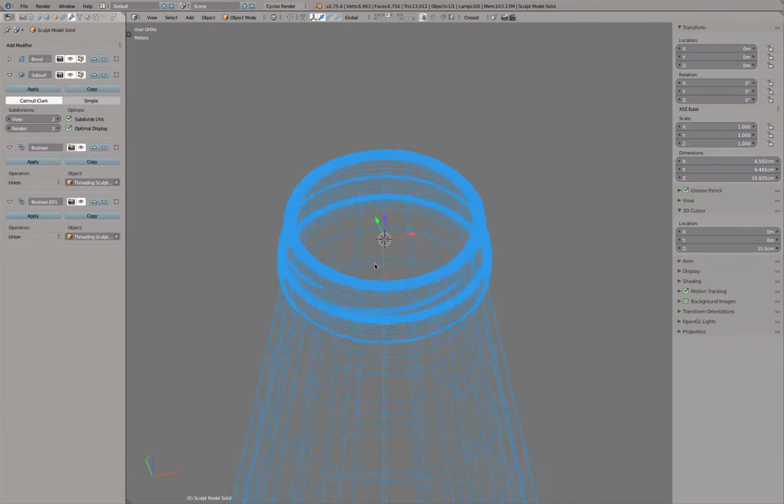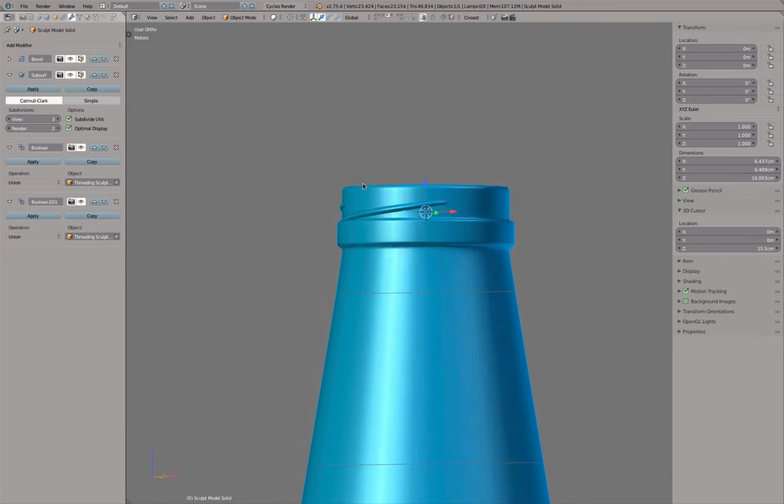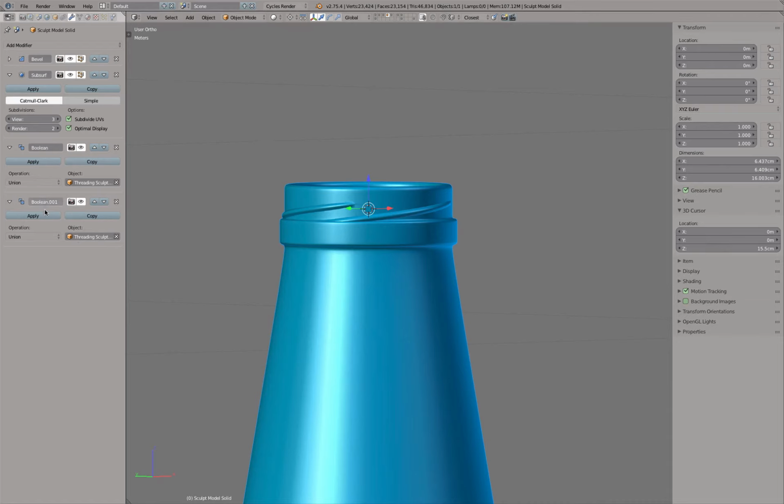If I go into wireframe mode, you will see how this geometry was added to it. And if I switch view here to 2, the results will be a tick better. But the higher the view level, the more polygons there are and the more the software has to calculate, so the longer the delays are. So try to keep this always at a 2 or 3. Never go to 4, 5, or even 6. I could, for example, now simply add the other missing 2 threadings. I'm not going to do this because then later this tree will be very full. I call this, for example, threading.